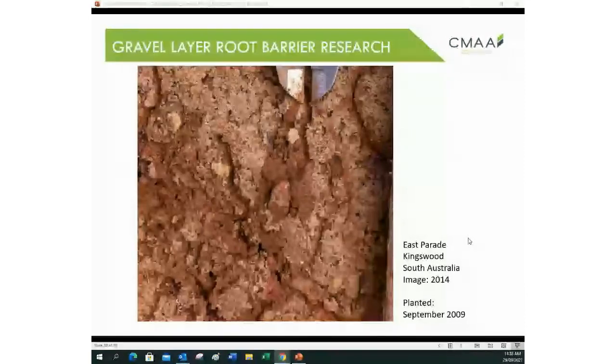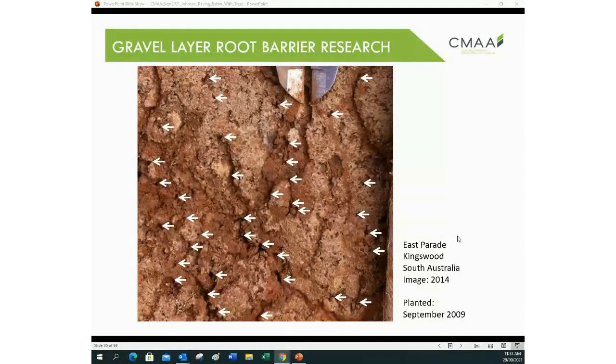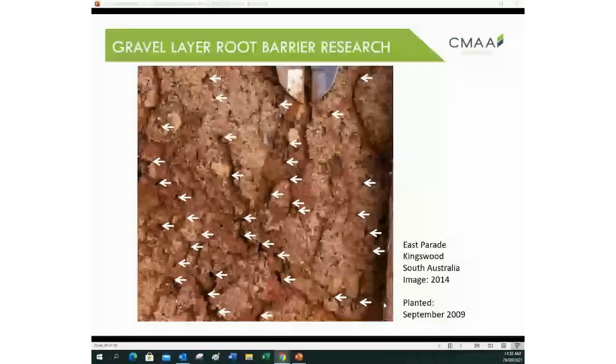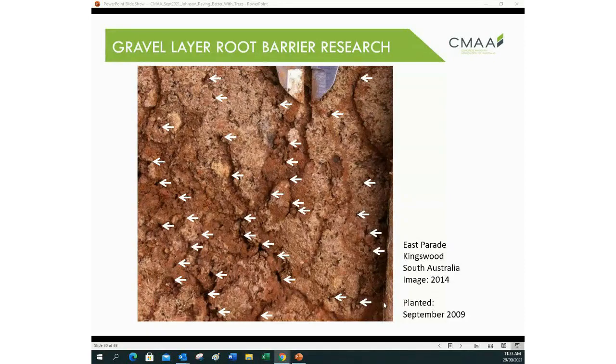But what's really interesting here is all of those tracks you see have a fine root hole that descends into the subgrade. So this is increasing porosity, it's increasing stormwater infiltration rate, and it's increasing oxygen diffusion into the subgrade. So the permeable pavement is designed using DesignPave and PermPave to be supported by this low strength subgrade. And this low strength subgrade is actually enhancing the stormwater harvesting performance of the water sensitive urban design device of the permeable paving. So we've got a greater volume of soil, restored soil moisture more quickly because of this porosity, more access to water available to the trees, so less intrusion into people's gardens, broken pipes, those sorts of things. Generally a better system starting to work more naturally.